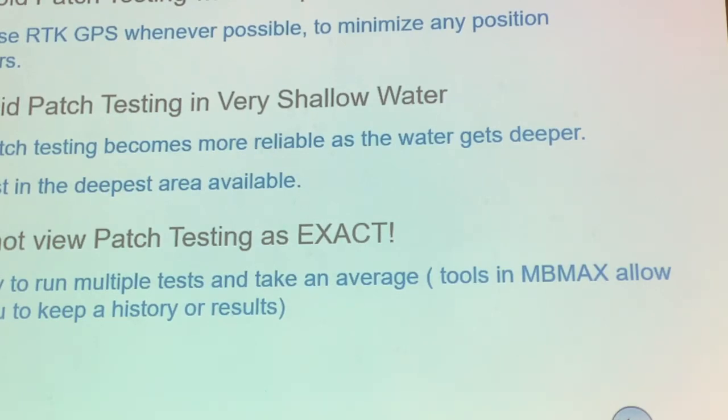make sure that your GPS is highest quality. Don't do low quality GPS for the patch test because if you do low quality GPS, then your patch test is useless. It must be the highest quality. Before doing the patch test, the GPS signal must be the best.